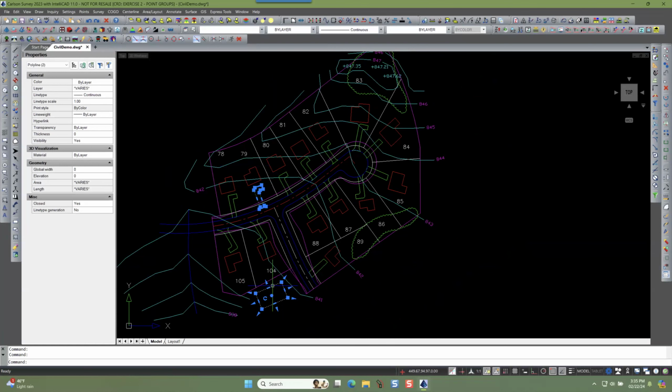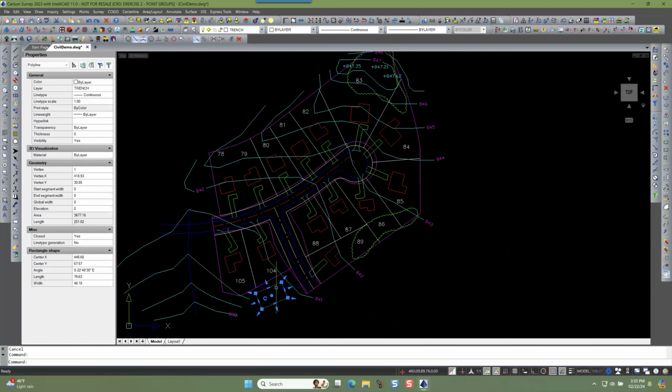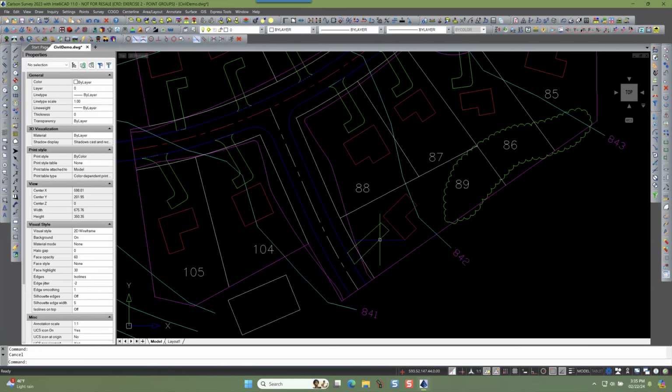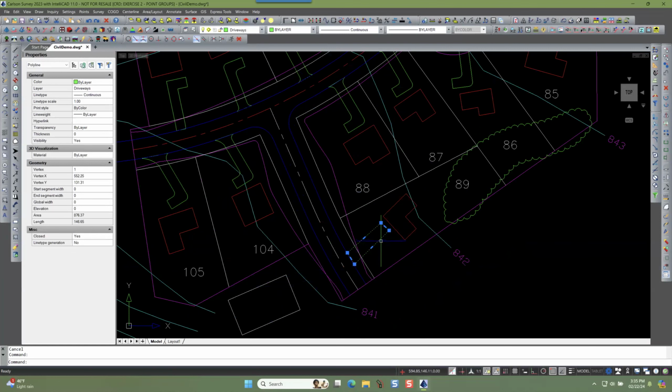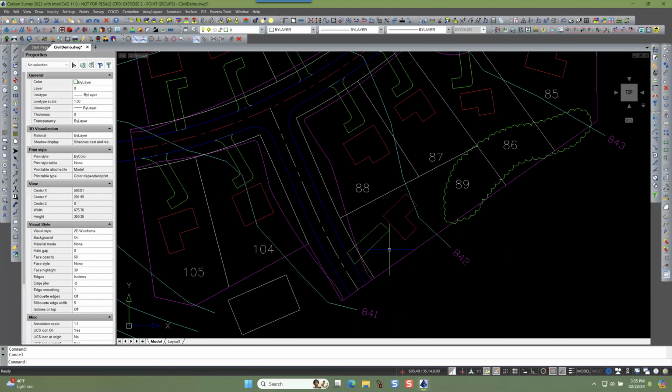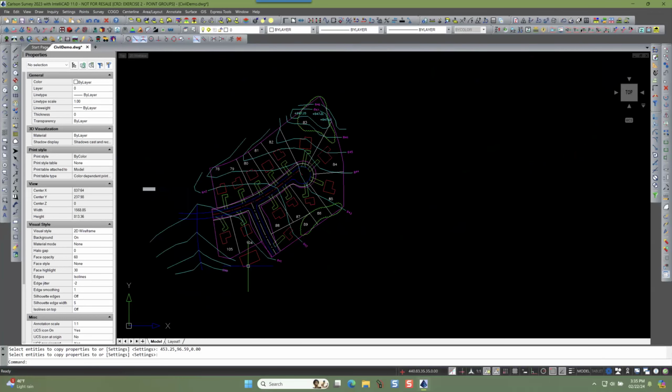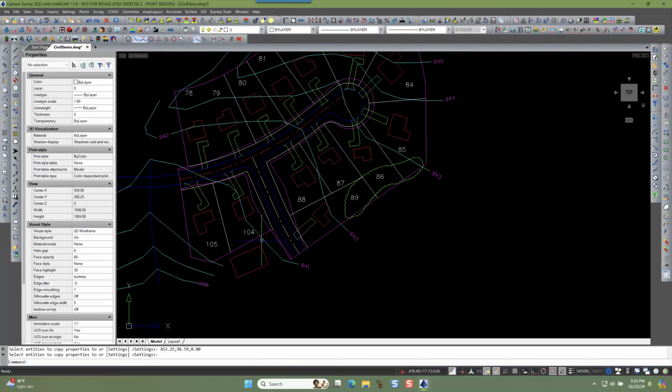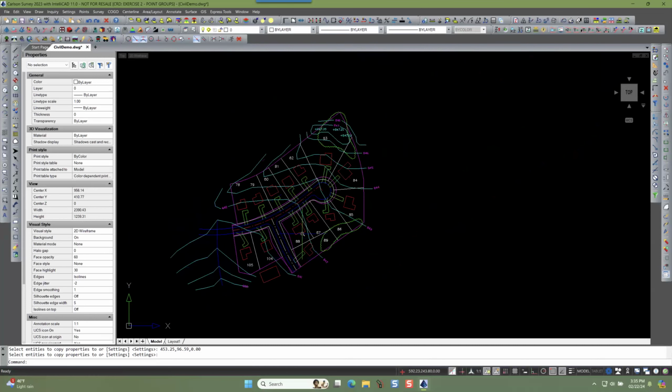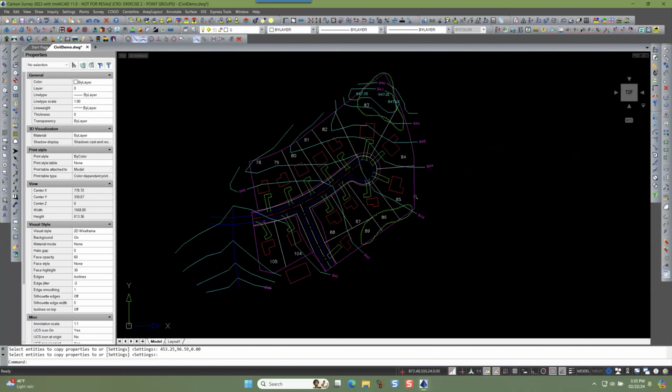this guy here, for instance, let's say it's a layer called trench. It probably should be on a layer called building. There's one called driveway. So I'm going to use that little paintbrush up there and match the properties. I'm going to set this building and that building. So that would be maybe a building, but it's off our property, so we're not going to worry too terribly about it. All right. So